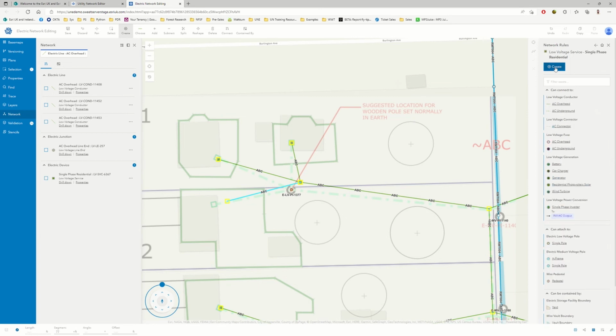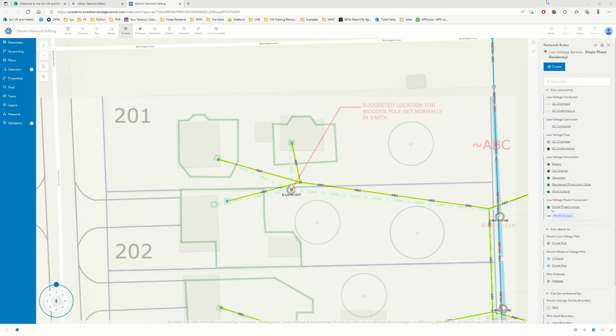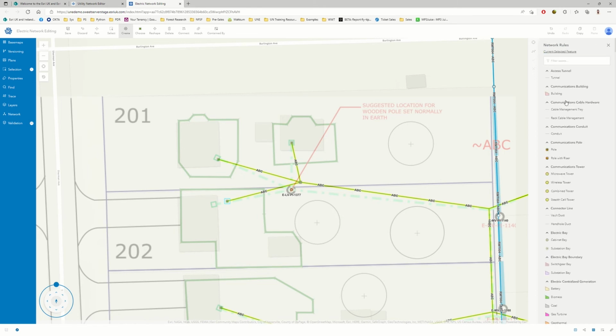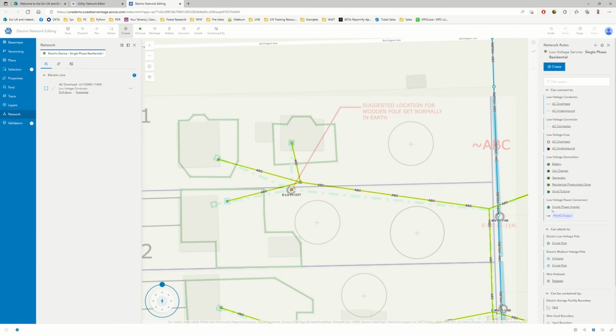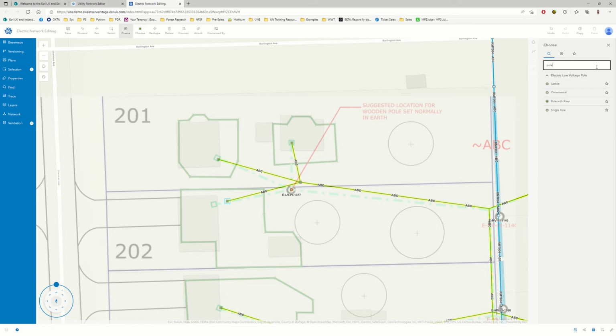So far, we have seen that this is a multi-step workflow, so we can do different workflows to perform the same type of task that we have been tasked. UNE can also help us with different workflows by allowing you to create group templates, which provide the users with a combination of multiple edits in one go. In this case, when we create a new asset by selecting the group template, this is going to create both the line and the service connection in one go.